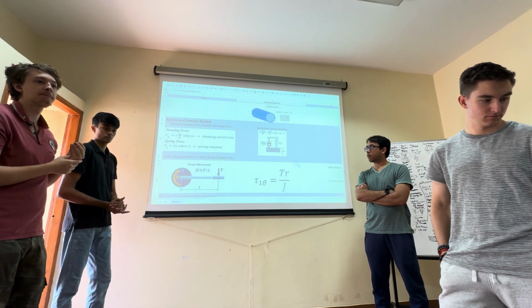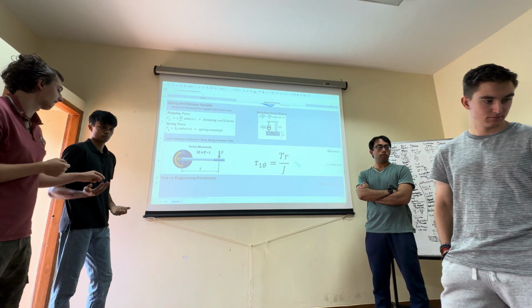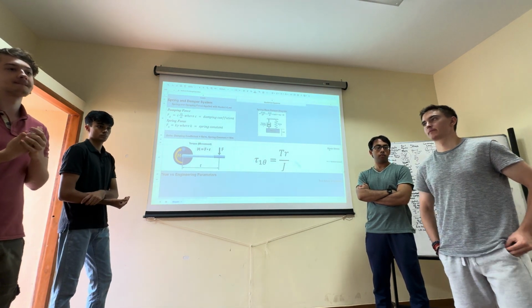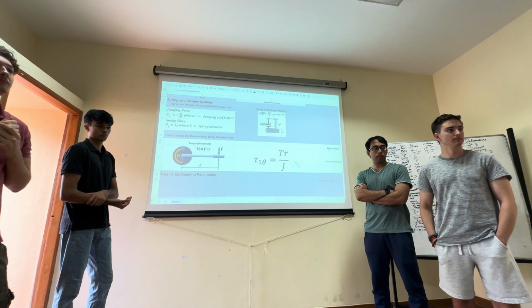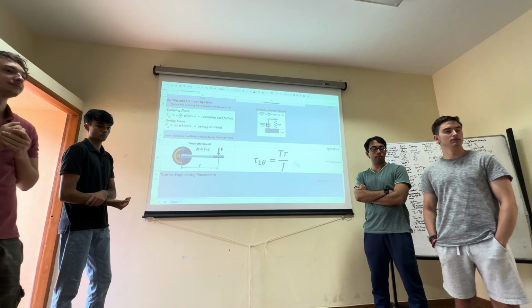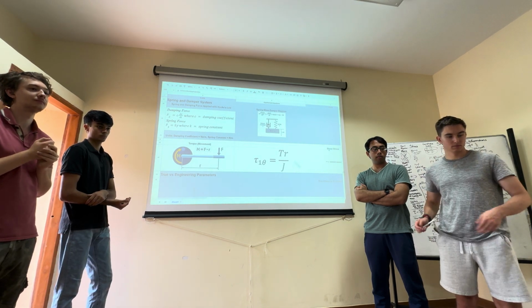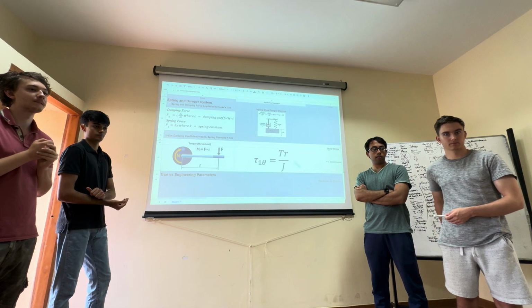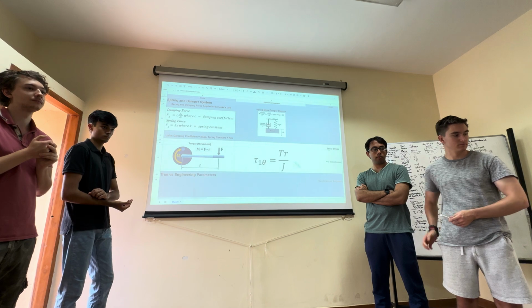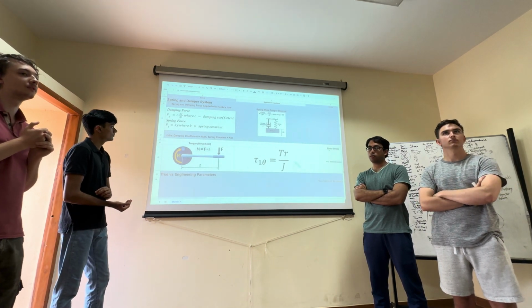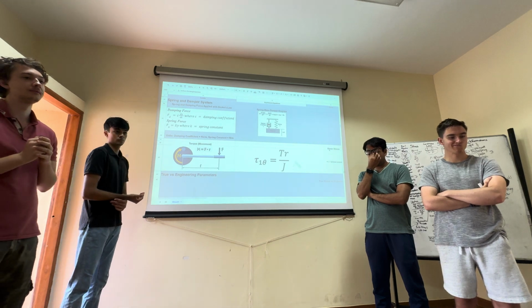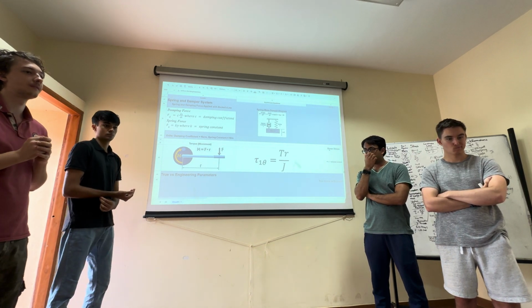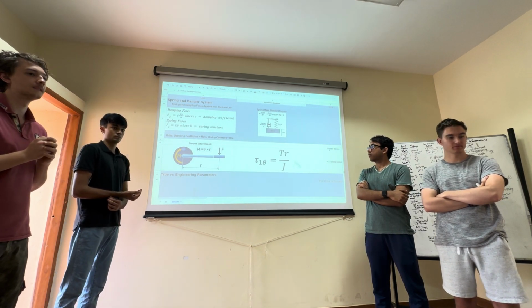Whenever we say pressure, we automatically mean negative normal stress. And the volumetric change is also negative because it's a reduction in volume. So if you're writing stress versus the volumetric strain, then you don't need the negative sign. But if you're writing pressure versus that, because pressure is assumed positive when it is compressive, then you do need the negative sign.